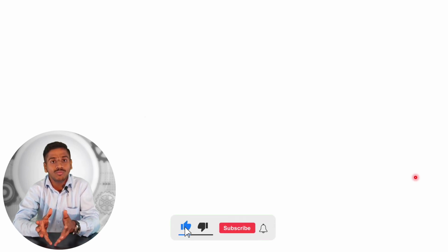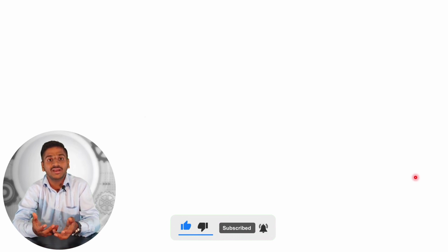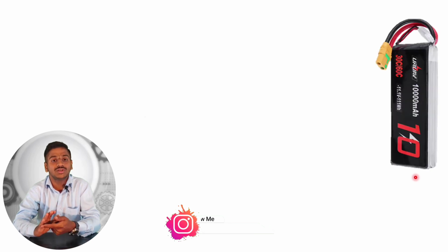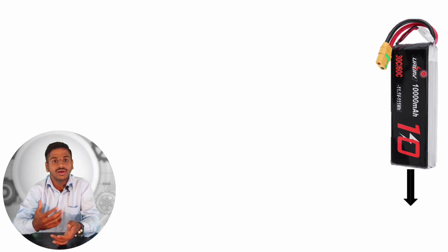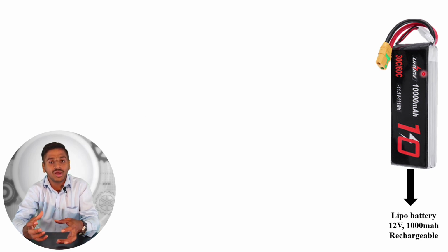So actually the whole model's power supply is going to come from the battery, because it is portable and we have to carry it anywhere. It's not like we have to give an AC supply and work in one particular location. So first of all we have used a Lipo battery of 10,000 mAh and 12 volt. It will be giving power supply to my whole 4 motors, the 4-wheeler drive which I have placed at the bottom, so that all the 4 motors are going to run forward and reverse on this particular Lipo battery.